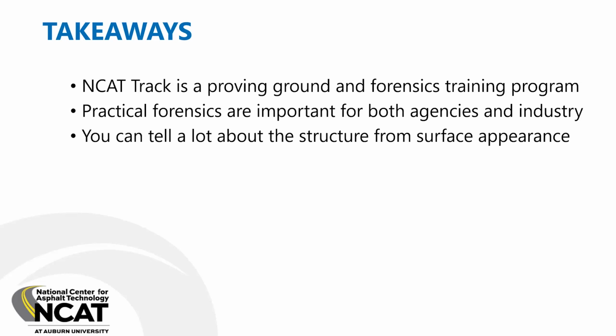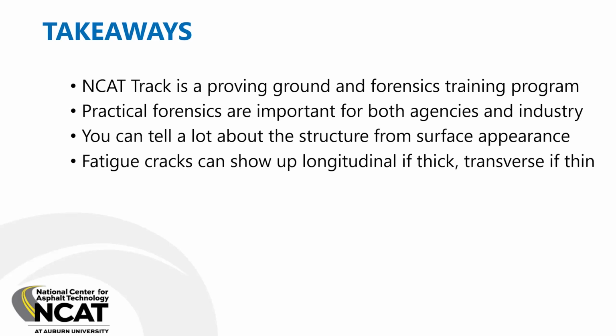Third point, you can tell a lot about the structure just from surface appearance, just based on what you're seeing about the nature of the cracks, the orientation of the cracks, that type of information. Fatigue cracks can show up longitudinal if thick, but in the transverse direction if it's thin.